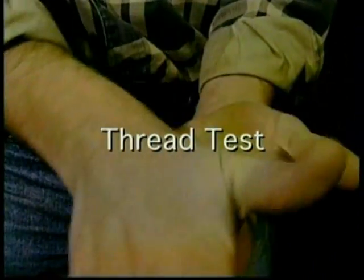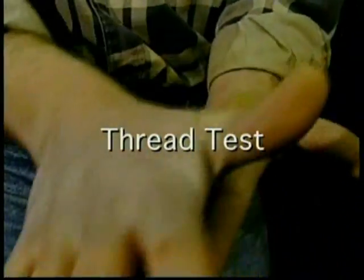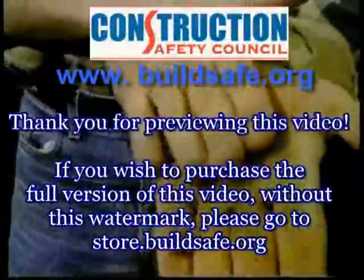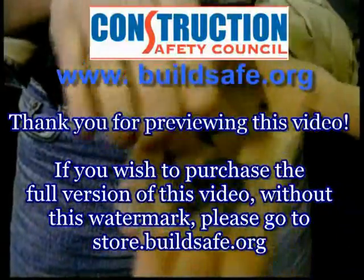Plastic means a property of a soil which allows a soil to be deformed or molded without cracking or appreciable volume change. The soil's plasticity can be determined with two tests, the thread test and the ribbon test. In the thread test, a sample of soil is rolled into a ball and then into a thread. The longer the thread, the more cohesive the soil. If it breaks apart, that indicates granular material, and the soil could be type C.